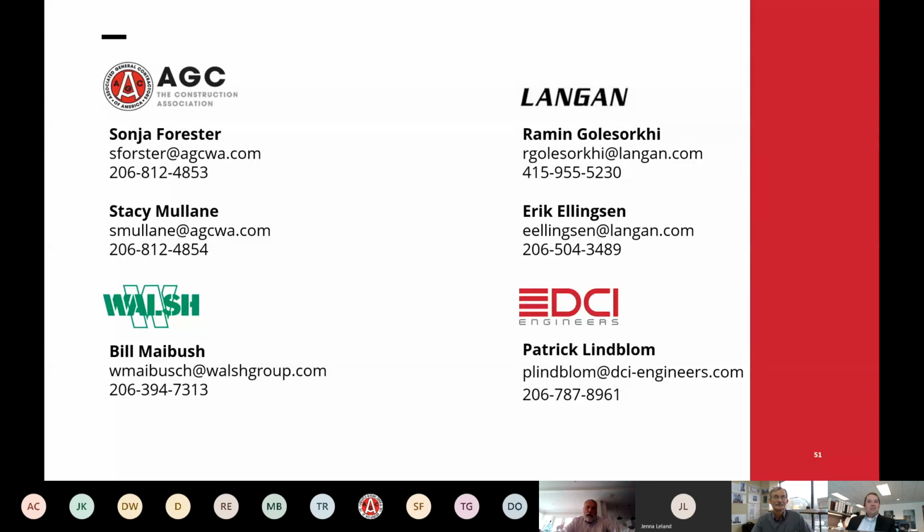Just to add, as I mentioned, the reason for the big changes in ASCE 7-16, which relates to the site-specific Chapter 21 of ASCE 7-16, these big increases were because we were going to go to the multi-period and these basin effects and all of that.